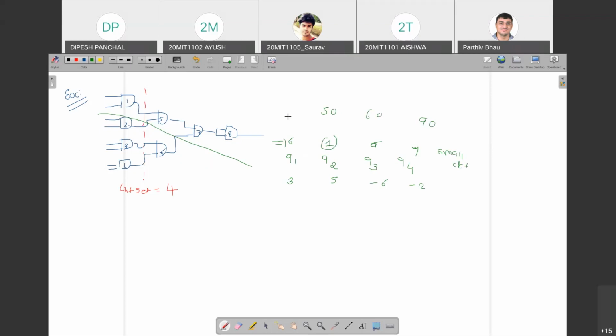So in that case, you have to apply second pass by selecting this pair as the initial partitioning, and check whether this number is reduced or not. If your circuit is complex, with millions of gates, definitely it will not work. It will not give the best answer just by one pass.